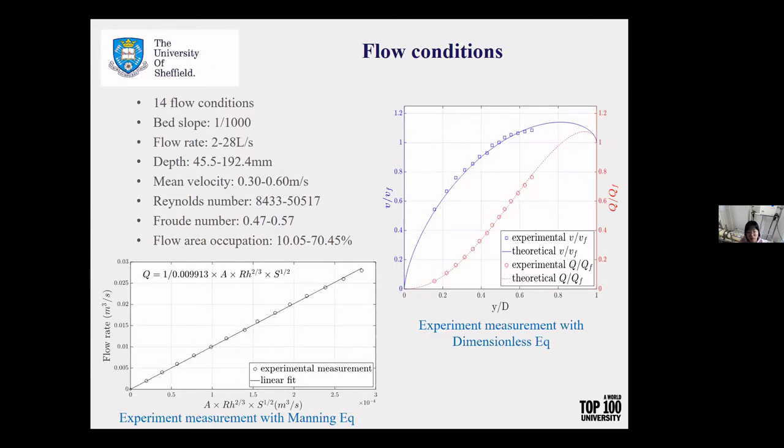14 uniform flow conditions with different depths and flow rates were examined. The measured flow conditions were validated against theory. The left figure shows the Manning's equation, and the right figure shows the dimensionless equations that show the validation of the uniform flow conditions.